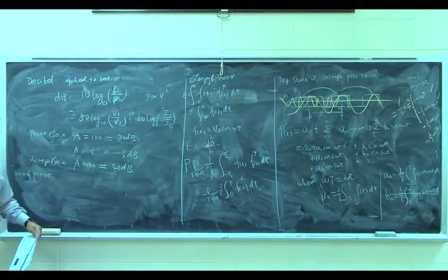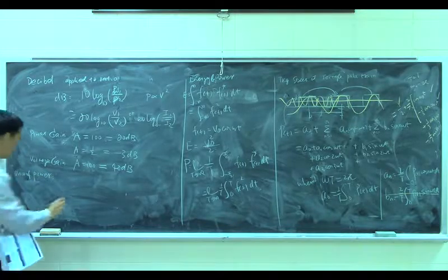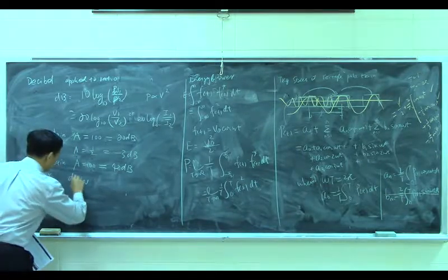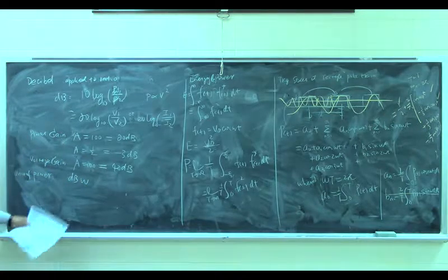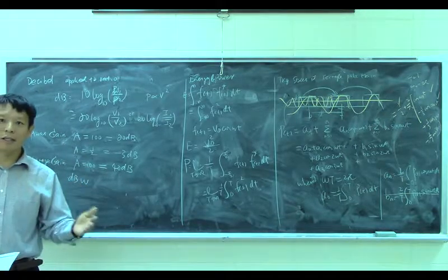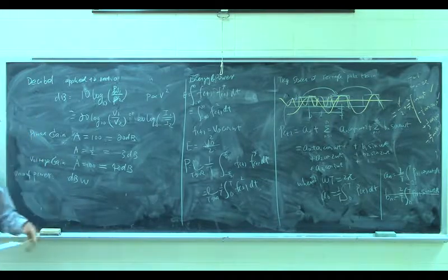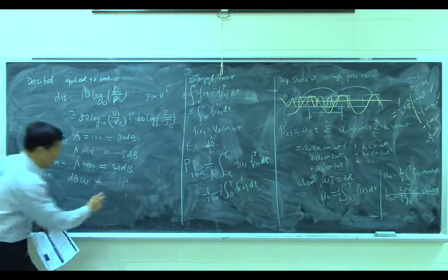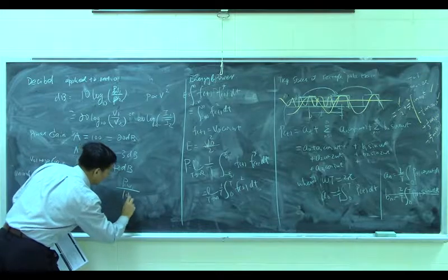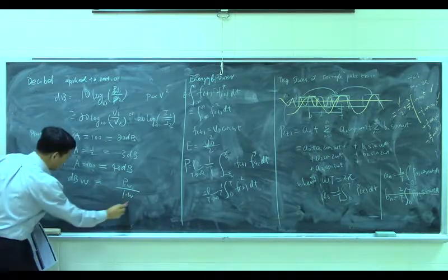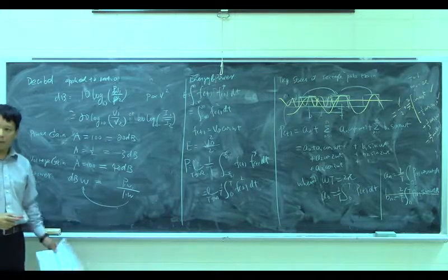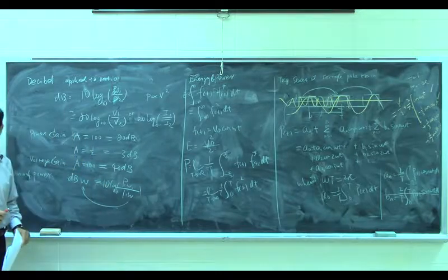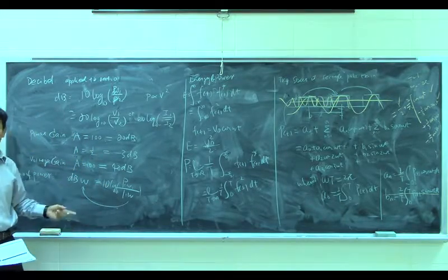The unit of power is what? Watt, right? And sometimes we do not use this one. We can use a dB watt. So, for example, this power equals 0 dB watt. What does that mean? That means it is your power in watt divided by 1 watt. Why divided by 1 watt? Because we are talking about the watt here. Then you take the log base 10, then you multiply by 10. So this value gives you dB watt.